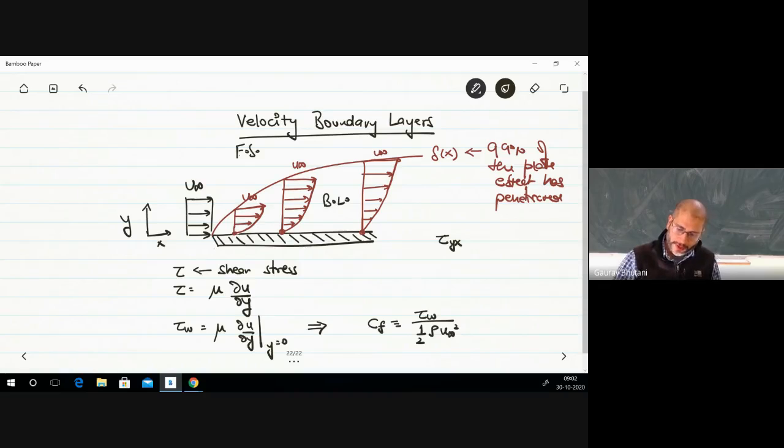And what we also saw in fluid mechanics is that the shear stress in general, as your y increases, let's take this situation, if I go up, then my velocity gradient del u by del y is decreasing. The parabolic variation: at the surface of the solid, your del u by del y is maximum, as you can see from the slope here.